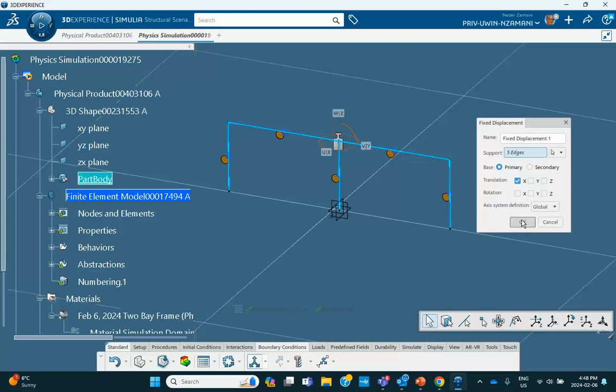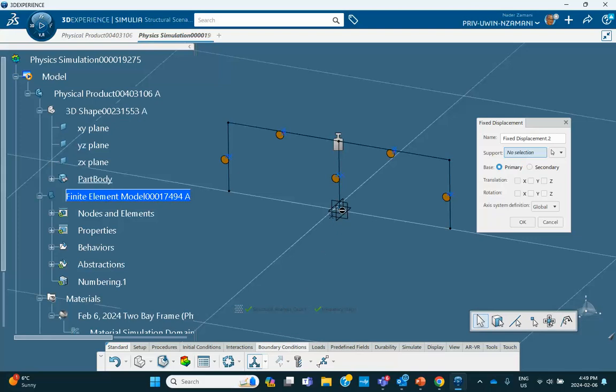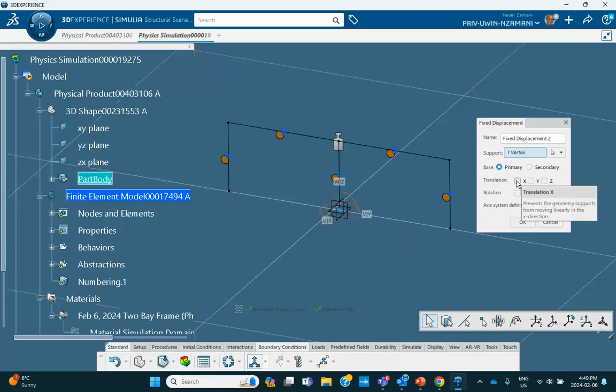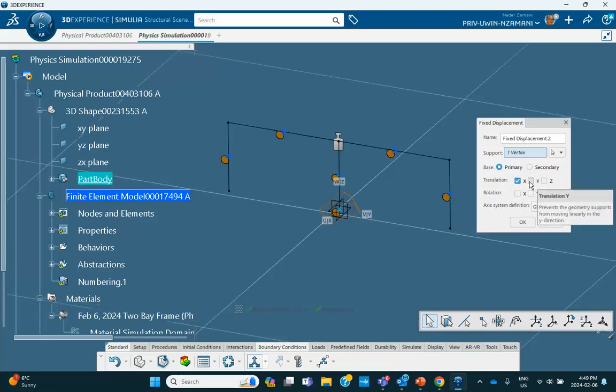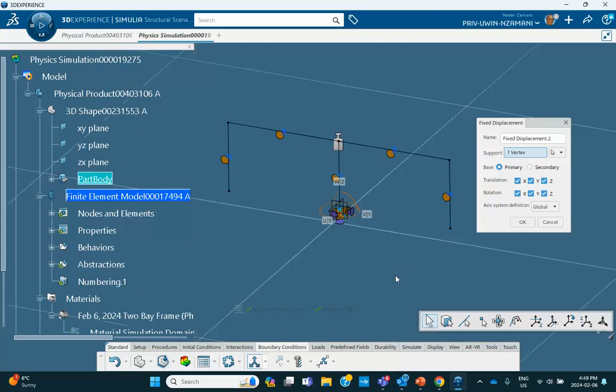Doesn't do anything. Now, this middle one, this point in the middle is actually a clamp. So you just go and apply a clamp boundary condition here, or you can say no displacement in x. Already we know that. I can take that off because already it doesn't move, but why not? Okay. So this is repeated twice.